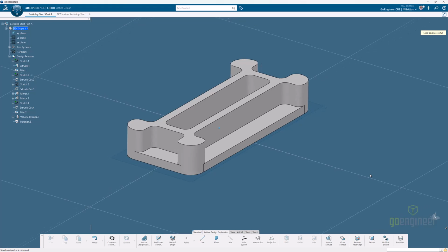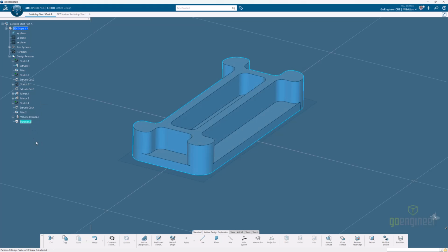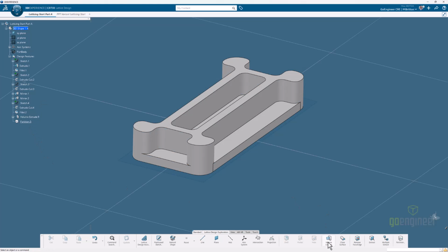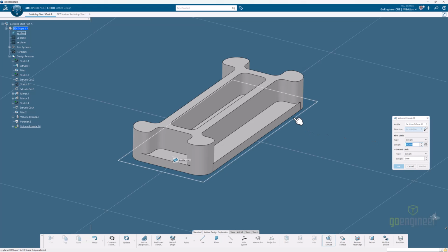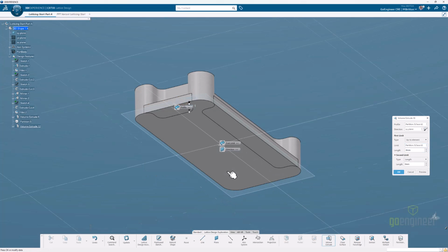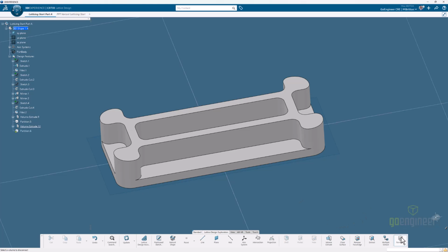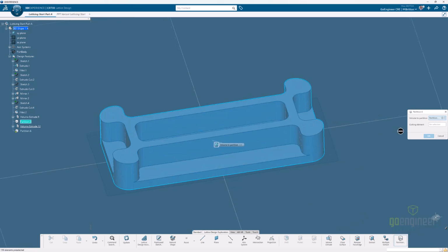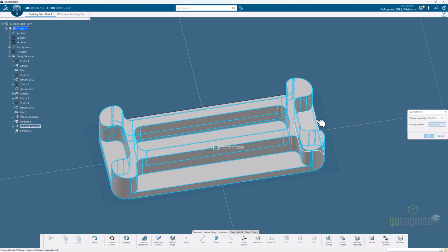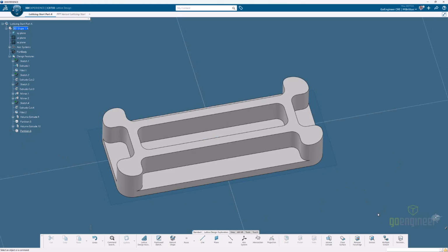And now all I'm going to do is come around to my other positions and do exactly the same thing. You can see I have my volume extrude 9 here and my partition feature there. So let's lather, rinse, and repeat 3 more times for these other areas. Volume extrude, choose my face, choose my direction, reverse, and select my limiter. There we go. Create my partition, select the volume, select my cutting element, say OK, and we'll continue onward.